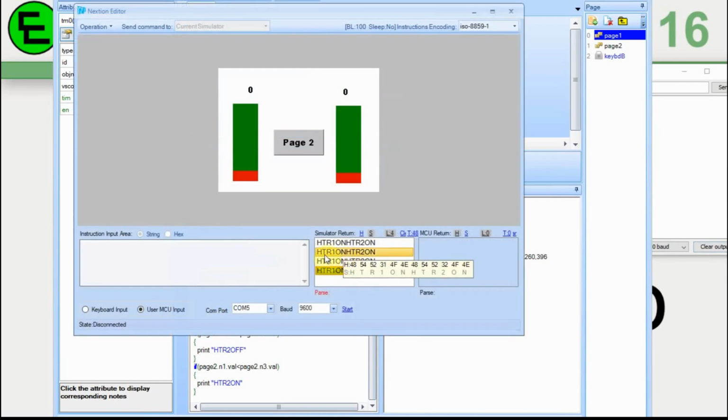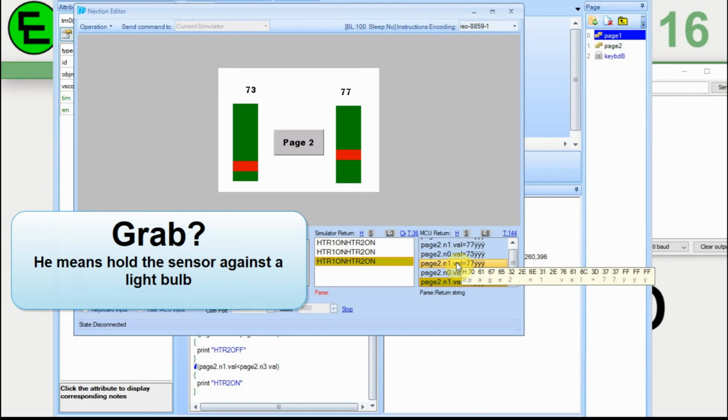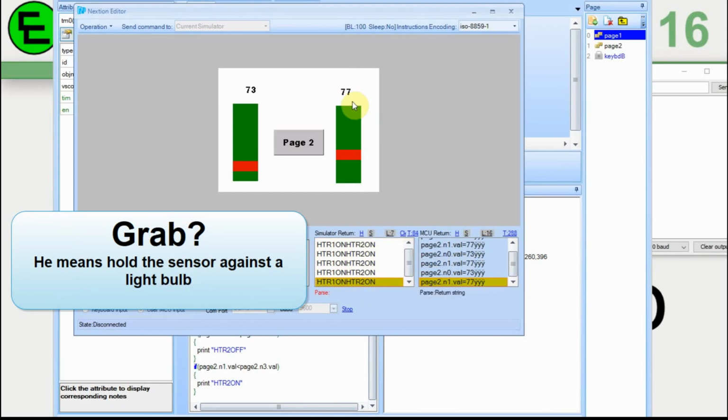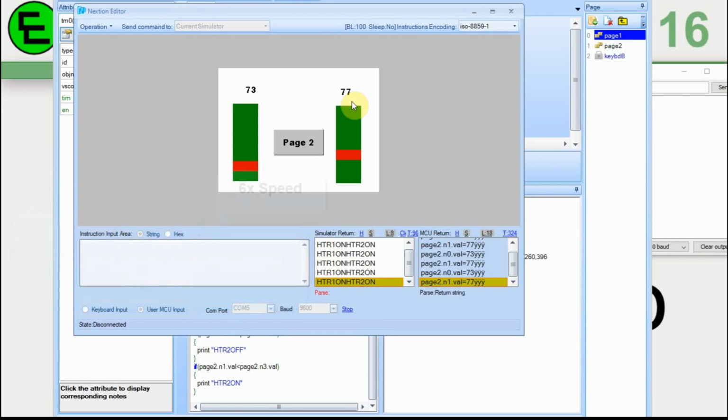And you can see here, we're sending heater on. And now we're going to start this. And we're sending the temperatures back. I'm grabbing heater 2 here. And you'll see that it will turn it off once the temperature gets above 80. What's interesting is at 80 exact, it doesn't send anything because remember it's less than or greater than 80. So when it sits at 80, it doesn't do anything. So now as the temperature goes back down, it will do the same thing, only it will change to on.